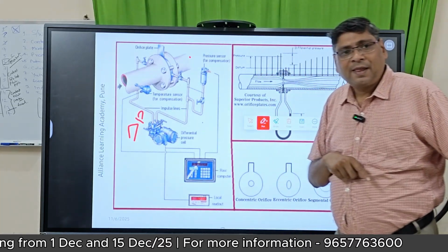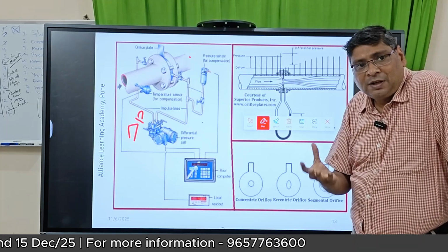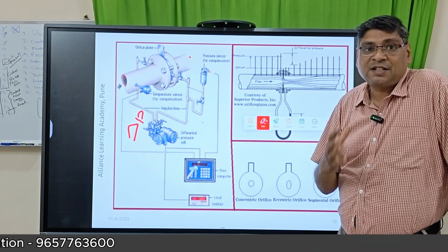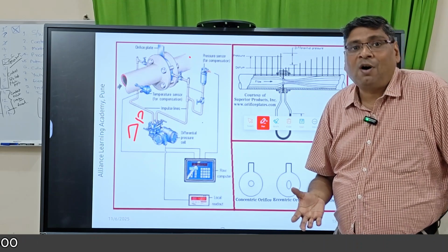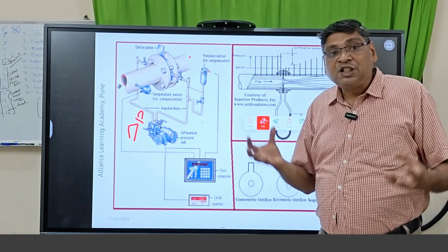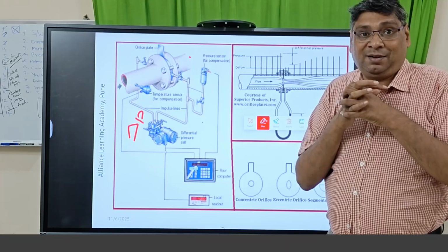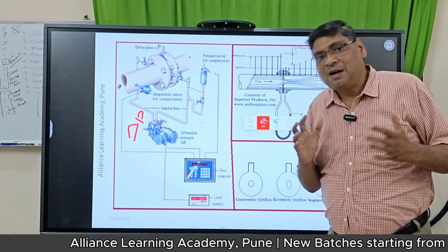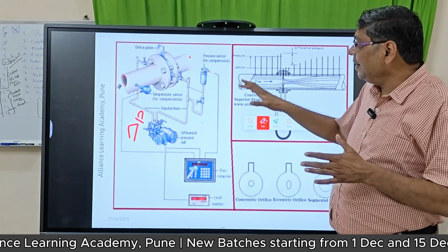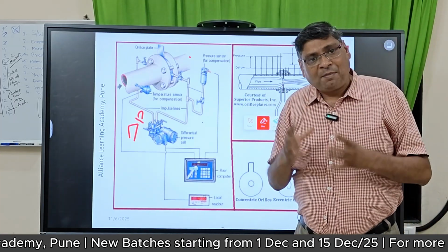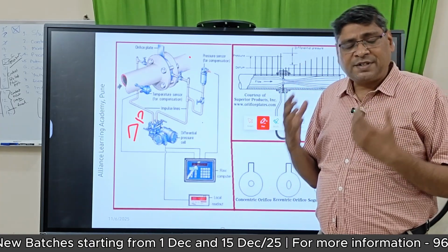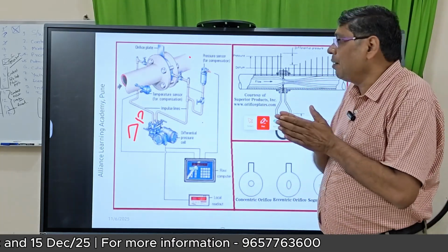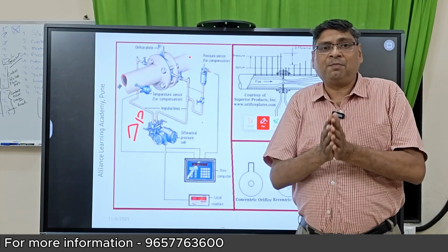Now, a very important point. If you remember the last session, I told you about density compensation, STP and TP. Why? Because gases and steams are compressible. That's why they need pressure and temperature compensation. So with any delta P type of flow meter, if it's measuring steam or any compressible gases or fluid, then we have to do the density compensation.